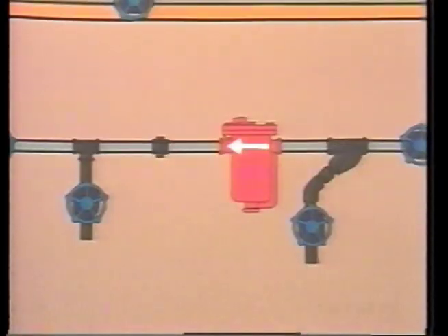One of the major causes of trap failure is oversizing. Oversizing is explained in your text, but the important thing to remember here is that if the trap fails consistently before it is 3 years old, check out the possibility that the trap is oversized. When installing a new trap, do not use size as an indication of capacity. Check the manufacturer's literature to be sure that the trap being replaced and the new trap have the same design specifications. This may be possible even though the traps are physically different.